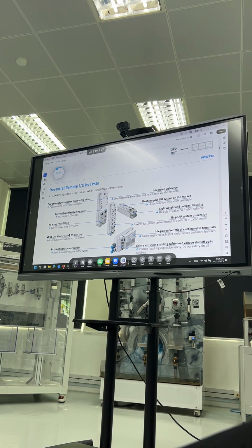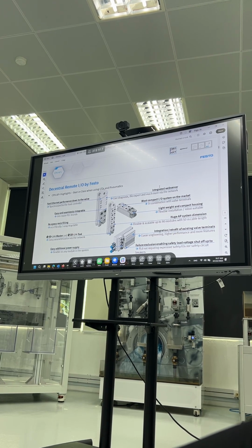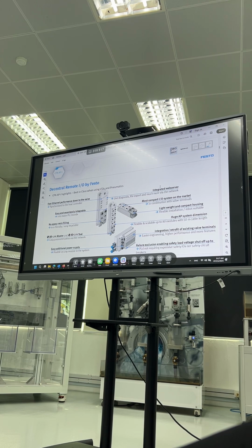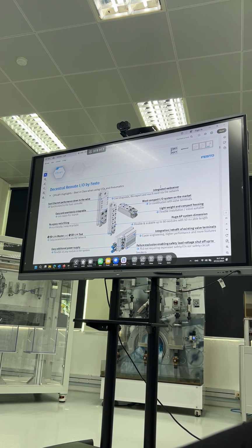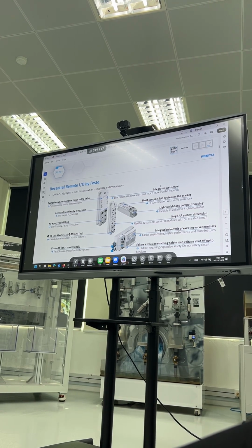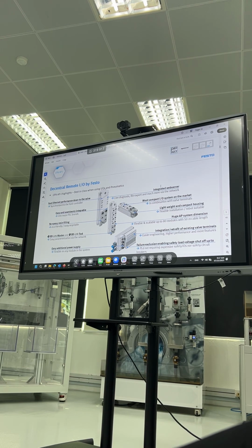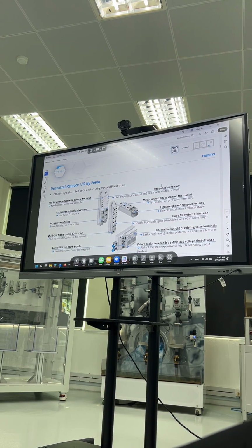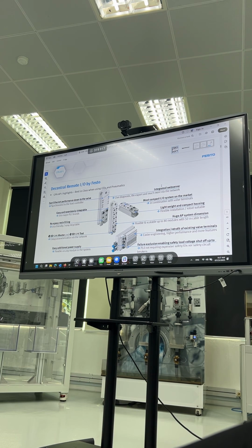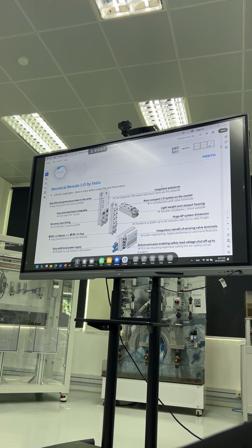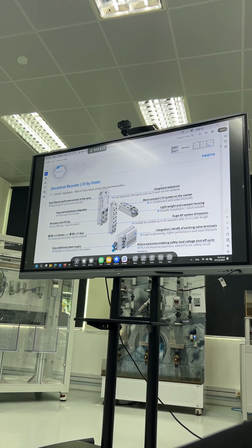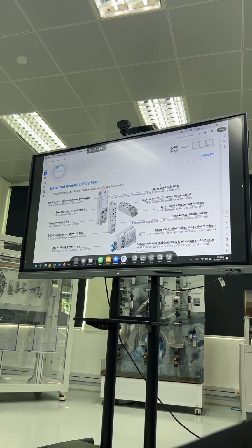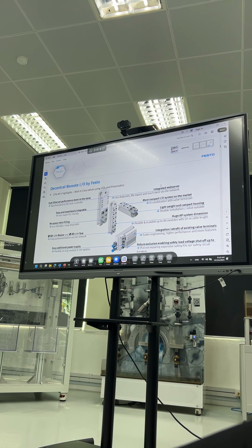For example, analog input, okay? Let's say the CPX AP analog input module. For the analog input module, it's freely configurable between whether the analog input is 0 to 10 volt or 4 to 20 milliamp. And you can do this configuration through the web server, or you can also connect it with our FAS. I think it probably mentioned here somewhere, I don't know. Yeah. You can connect with FAS and then you can do the configurations on the interface.